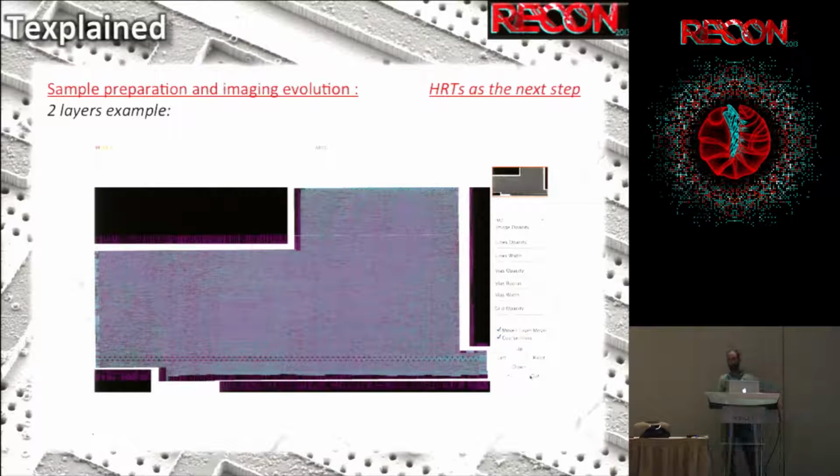But when you want to align the 2 layers together, you don't speak about resolution or magnification. It's grids that you align. So it will align perfectly. And you will have no error of stitching for 1 layer and no error for the alignment of the layers. And basically, once you have this, as everything is polygon, you can just convert this to a netlist. And now you have the netlist of the full core.